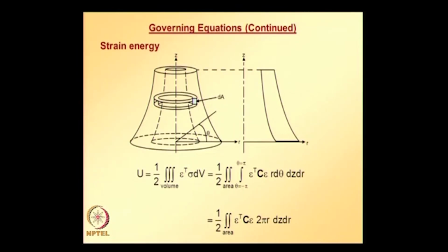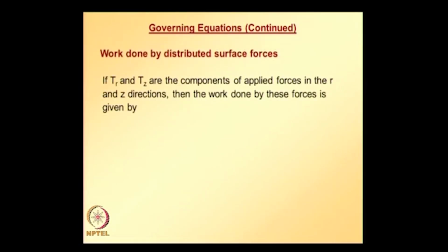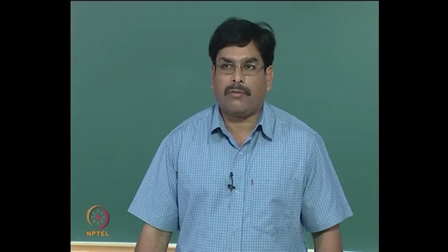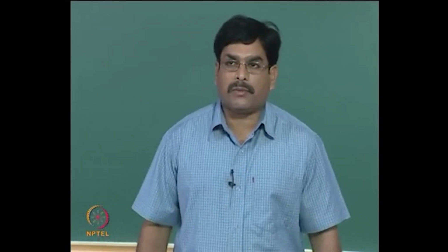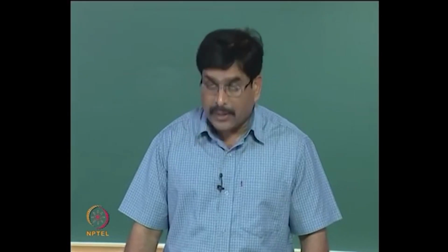Now, work done by the distributed surface forces: if T_r and T_z are the components of applied forces in the r and z directions, then work done by these forces is given by this. Evaluation of this strain energy and work done by the applied forces is very similar to that of the plane stress plane strain problem, except that we need to take care of geometry. That is why you should pay a little bit of attention to that.